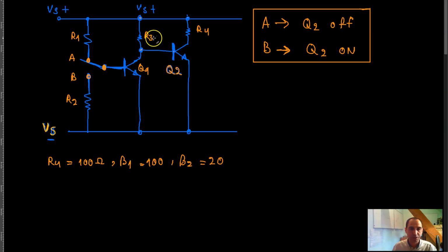So essentially, if this transistor Q2 was supposed to be turned on, then of course you would need to have enough current flowing here. Let me see what sort of supply voltage we have here. The supply voltage over here is 10 volts, right? So if this transistor is supposed to be turned on, you want the whole supply voltage to be dropped across this resistor. So I simply apply Ohm's law to this resistor to see what is the current in this branch.